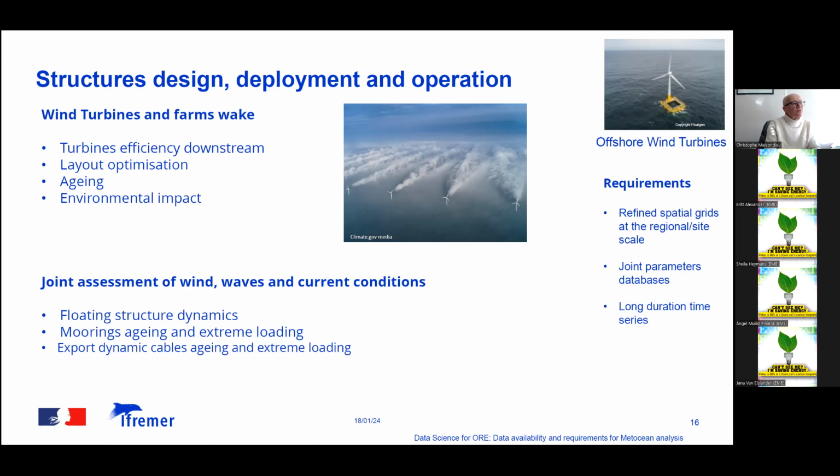There are other issues also, mainly related to the case of floating offshore wind turbines or planted offshore wind turbines. It's the impact that the waves and the current on top of the wind will have on the design of the structures. So the floating structure dynamics will have to be assessed, but also the extreme loading induced by the waves. Same for the moorings and the export dynamic cables. The loading will be induced mainly by the waves and the currents. So it's really important that we assess this as well.